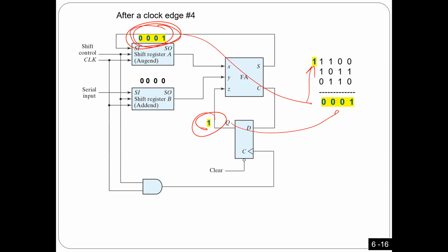It's slow because here I need 4 clocks, 4 cycles of the clock, in order to get the whole addition. And the idea is that because I'm using a shift register here, every clock I'm going to shift 1 bit. So, as I explained, you add these 2 bits here, you shift the result back to here, okay? So here you can have less hardware because you need only 1 full adder, but it is slow because you need 4 clocks to do it, okay?